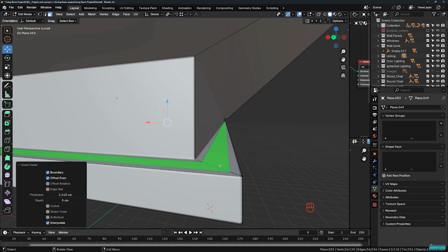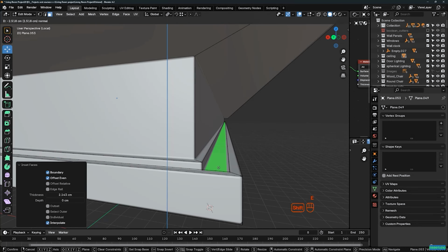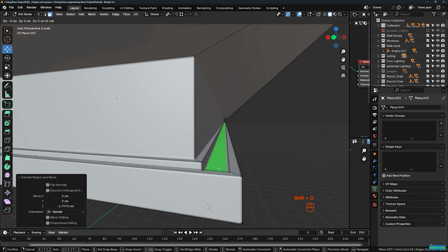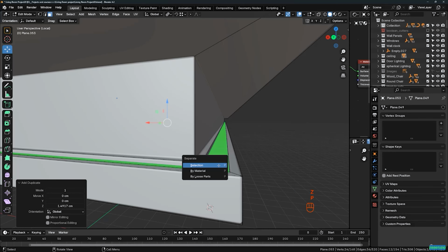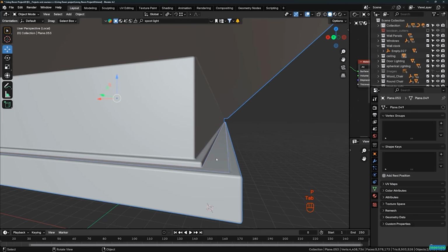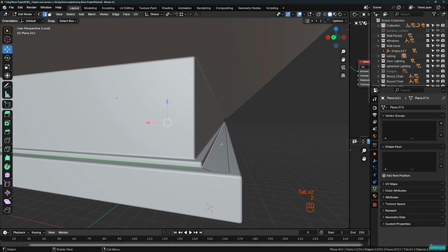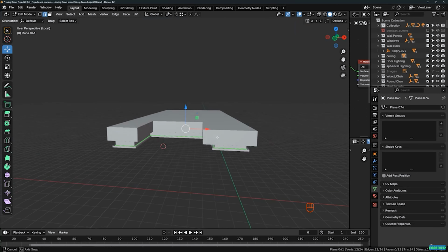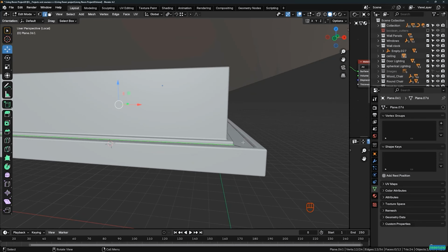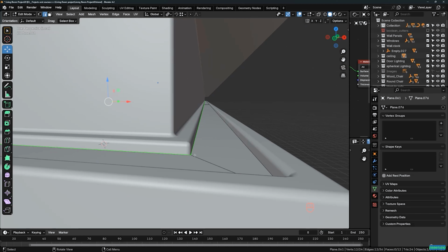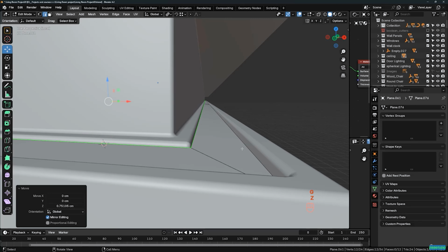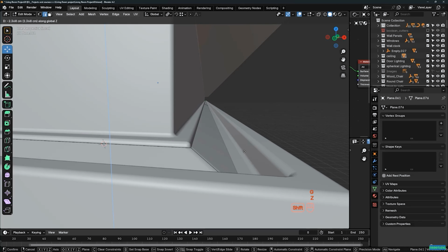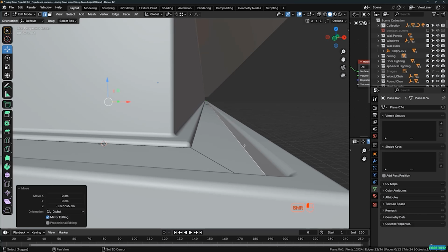And then I can use this and change this to a light. I will hit E to extrude this inside like that. And then hit Shift D to take this up a little bit like this. And then hit P and then S to separate it. Tab out and grab this new piece, tab in, go to the edge, select the entire edge loop, and move this up a little bit because we just want to change the direction a tiny bit. G to the Z and move this up like that. Alt click on this one, G to the Z and move this down. Something like that.